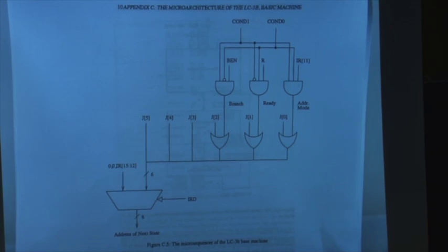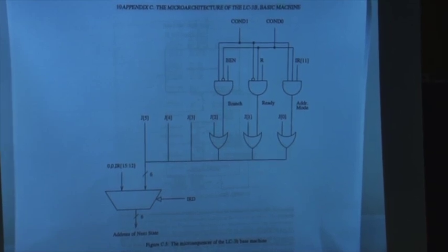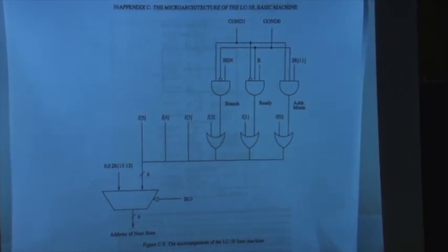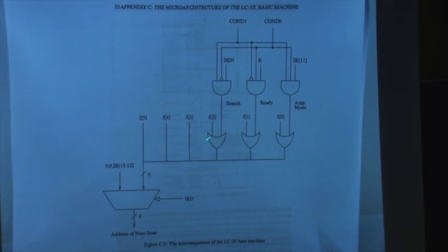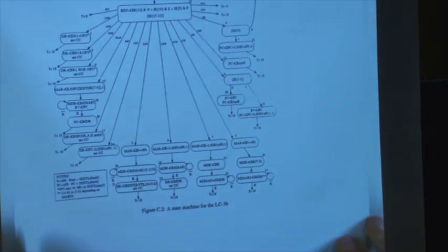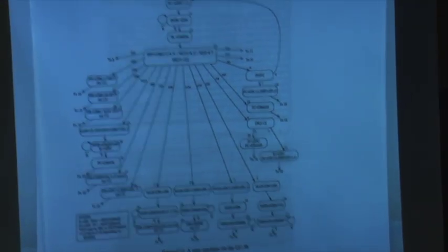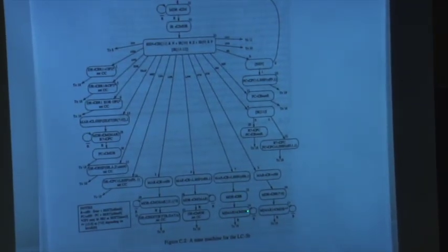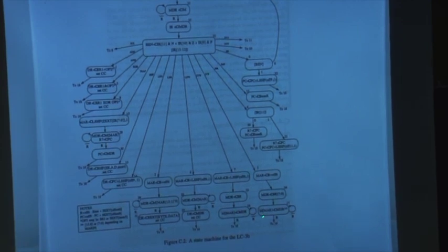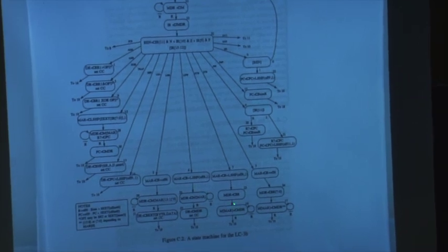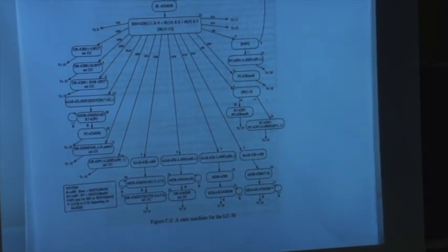So that's how you implement an unconditional state transition. Now the problem is, what if sometimes you have a conditional state transition? If you look at this, there's one case in the state machine, because the state machine is designed this way, and these are the cases. This is the store word and store byte instruction. You have 2 instructions that store. Once the store is done, you go back to state 18.